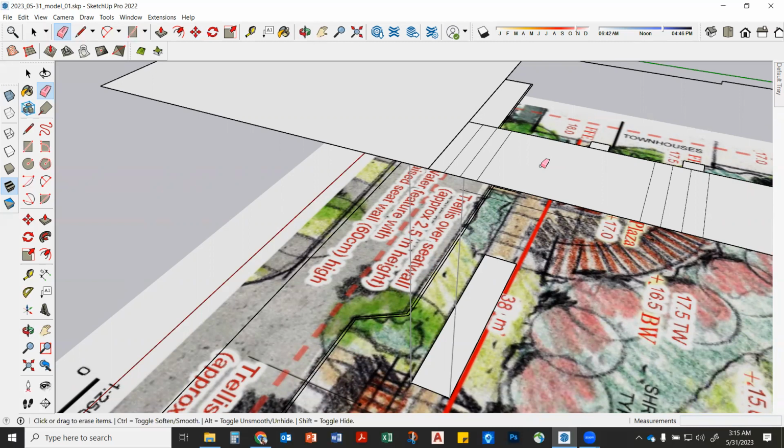Just making sure that you have positive drainage. Why do we need positive drainage? Because what? Why do we need positive drainage? Yeah, to move stormwater, right? Do you guys get rain here? Do you? A little bit? Sometimes, right? If it doesn't slope, what happens to the water? It's just gonna be sitting there, right?